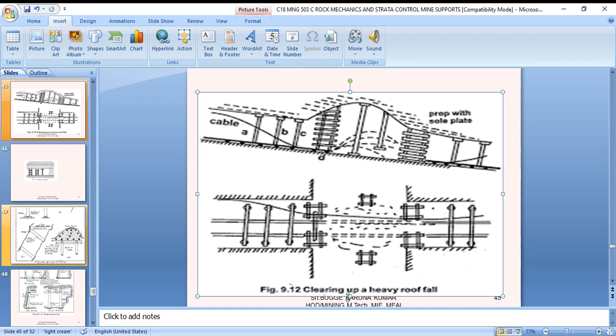If the coal pillars are not strong enough or the road is through a fault zone, the wooden bars are supported on timber props. This is a common practice where the roof pressure is likely to be heavy; bars may be supported on timber chocks. So for heavy junctions, these types of support systems are used.